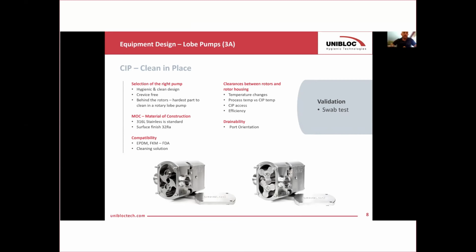The compatibility, the EPDM and FKM are industry standard, and you will most likely be fine using those, but there are also applications where higher grade elastomers such as Kalrez may be required in order to be compatible with the application and also with the type of cleaning solution that you will go with.